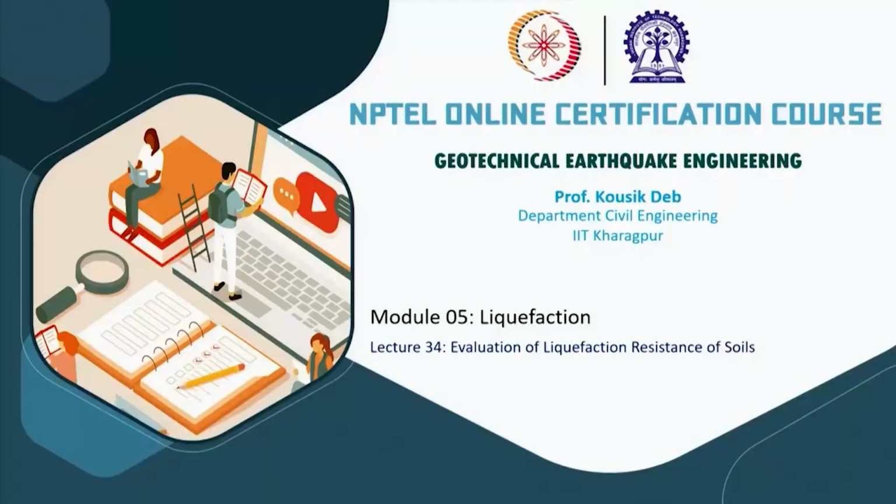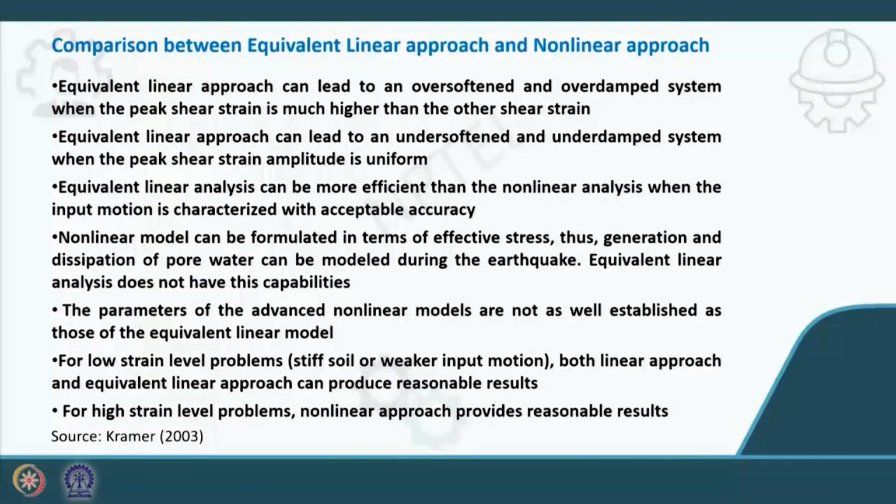Now if I compare the equivalent linear approach and the non-linear approach, these are the differences. You can see that the equivalent linear approach can lead to an over softened or over damped system when the peak shear strain is much higher than the other shear strains. Suppose you have your peak shear strain.